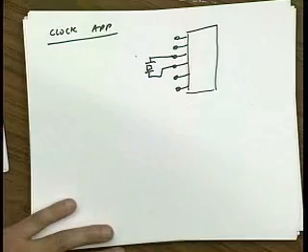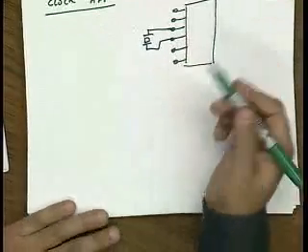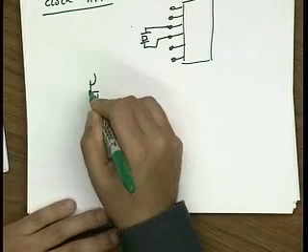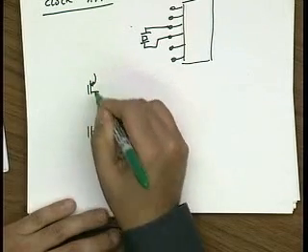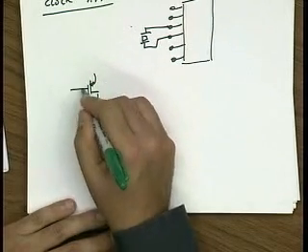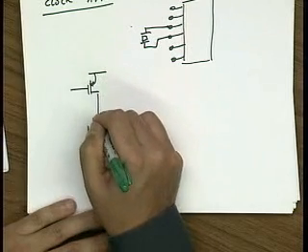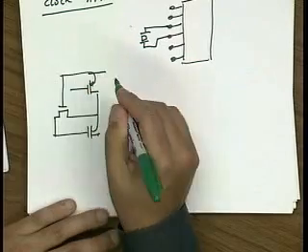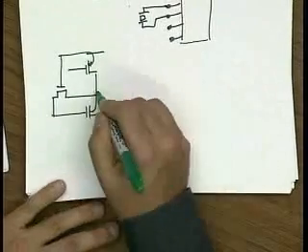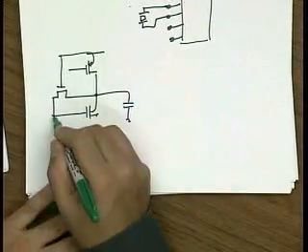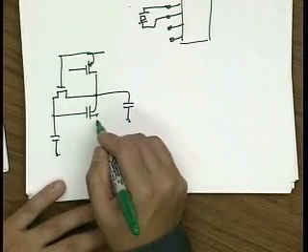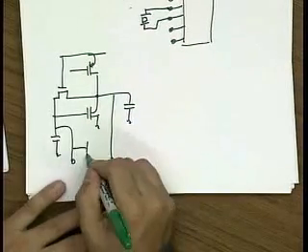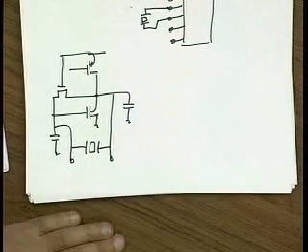And the nice thing about this Pierce oscillator is, let's say in a MOS technology, you might realize it as follows. This is your current source, and you might have a feedback resistance to bias up your circuit. You have your C1 and C2, and then basically you have pins that come off chip where you can connect your crystal.